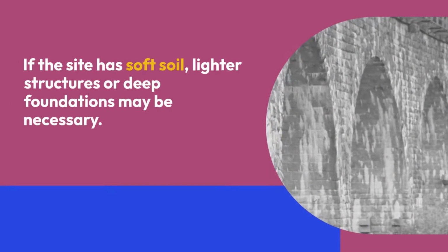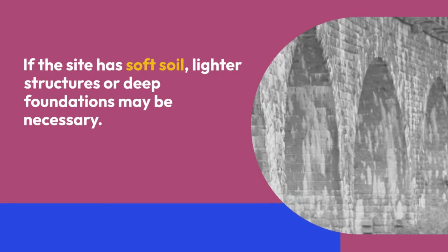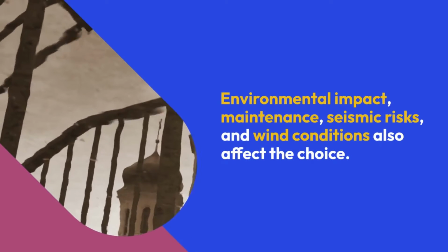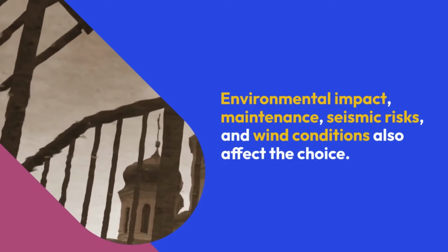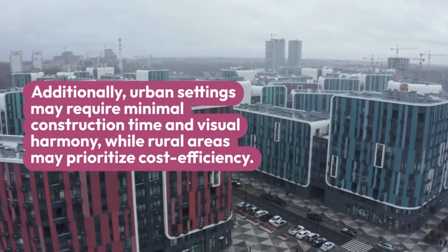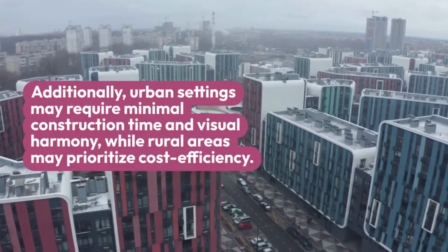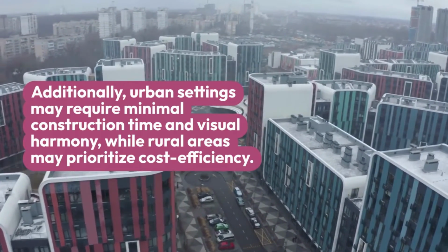If the site has soft soil, lighter structures or deep foundations may be necessary. Environmental impact, maintenance, seismic risks, and wind conditions also affect the choice. Additionally, urban settings may require minimal construction time and visual harmony, while rural areas may prioritize cost efficiency.